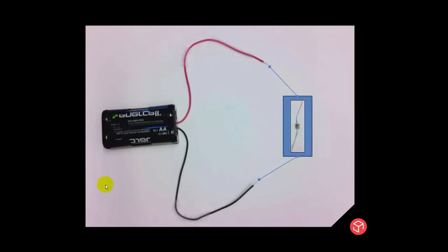Let's take an example. In here, I have put a resistor across as a load, and so it is ohmic. Let's assume that our power supply supplies 3 volts, and this resistor is 10 kilo ohm. What will be the current that will flow in the circuit? The answer is 0.3 milliamp. Why? As you can see here, the voltage, this is Ohm's law, is R times I, so I is V over R. V is 3 volts, R is 10,000. That leads to 0.3 milliamp.